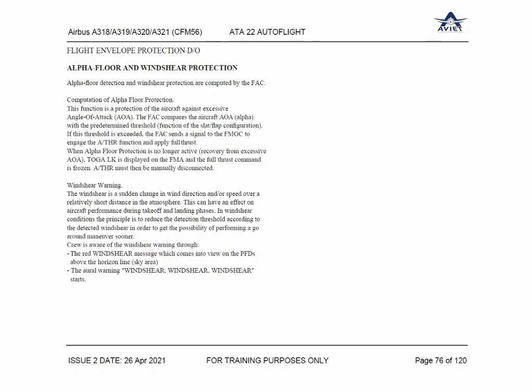Below 100 feet radio altitude, it will not apply. During approach, if you are in takeoff configuration, the whole sky is open; you can go anywhere. But if you are descending, you are nose down, and if you apply TOGA at nose down, you will crash. The aircraft will be like a rocket.